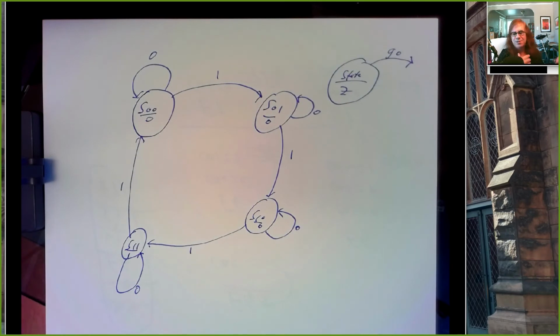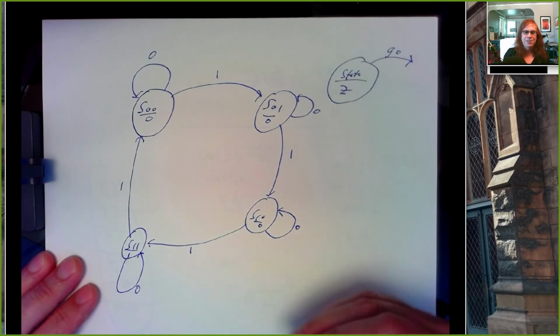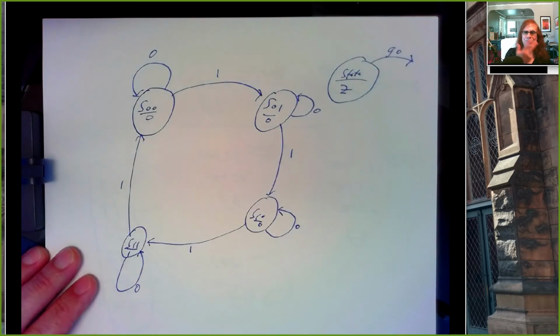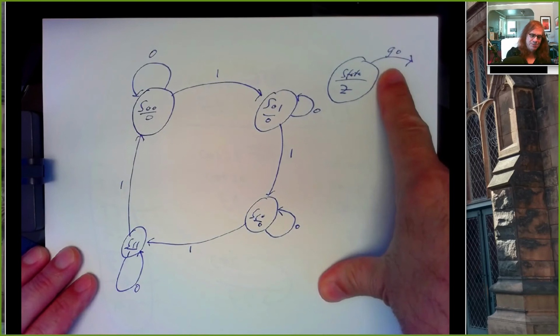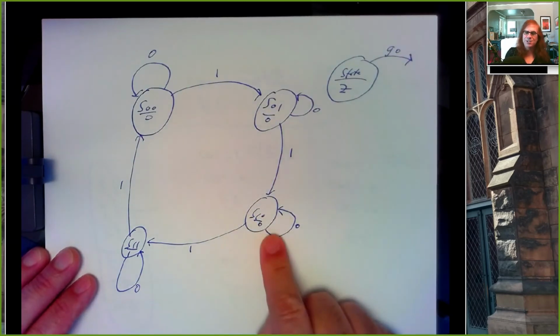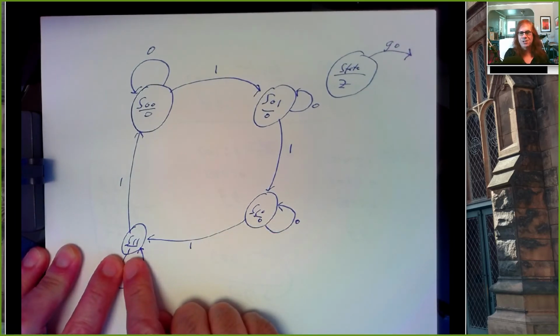So we've done this in homeworks and such, and it's a bit of a pain to do, right? Big wide tables and flip-flops and K-maps. If we tried to do this in Verilog directly, it's something like your traffic light experiment. You would have something that tracks our current state, so a 2-bit register. If our state is 0 and go is equal to 1, then let's change our state to 1. If our state is 1 and go is 1, let's change our state to 2. And let's set our output to 1 if our state is 3, otherwise set our output to 0.